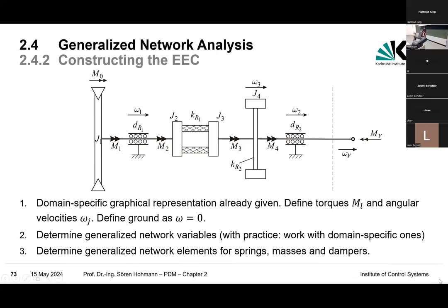Well, the turbine, to boil it down, can be replaced by some sort of rotational inertia. That's it. And then I have it. The bearing is something like a resistive element, right? So there we have a resistor. And there the flexible coupling, well, in practice it's some sort of difficult nonlinear material, but let's try to represent it by a linear spring. So easily.